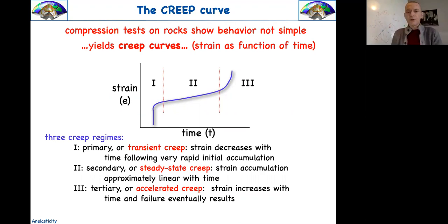And so generally, to study what is the strain inside a real rock in time, and now you see here, we don't have to imagine seconds, minutes, or hours, but maybe years and millions of years, whatever. So you have a regime where you apply a stress, you get the strain, that's the elastic if you want. You can call it transient. Okay, you're going to shear. If the stress is not that much, it's going back to the equilibrium. But then what happens later is that there is a slowing of this creep. And in any case, strain is going to be accumulated in a linear fashion in time. Then you may have accelerated creep. But the only word that I want to highlight here is creep. And creep is a general word that tries to describe how something is going to deform in time.